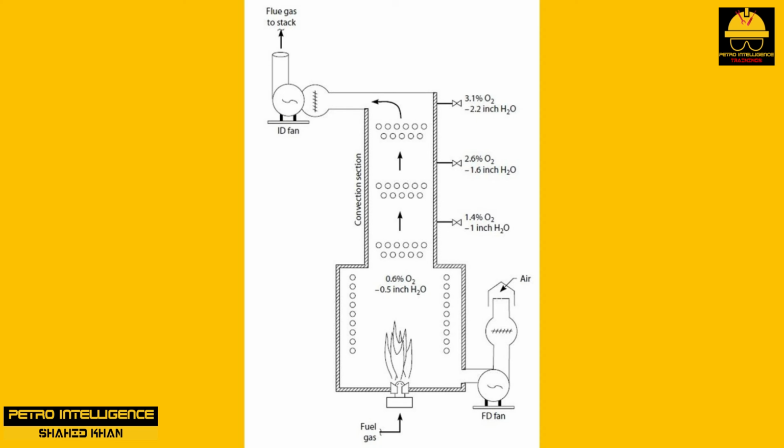If anything like this is happening to your fired equipment, open up the air registers, get more air into the firebox, and patch the leaks.